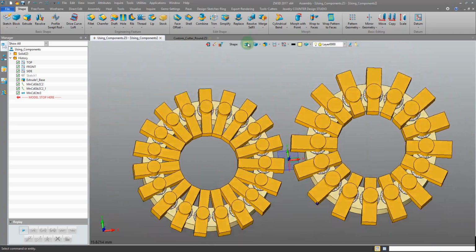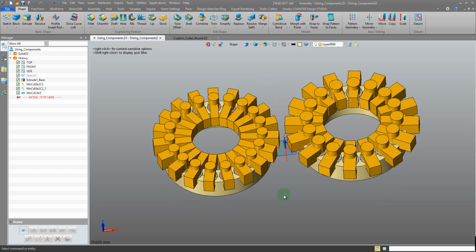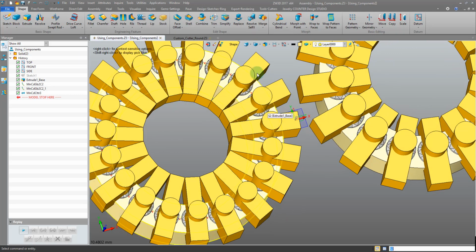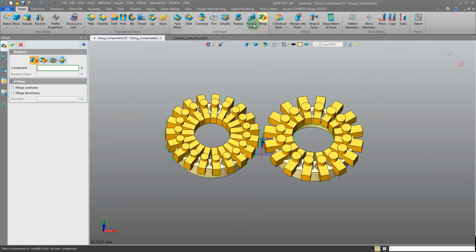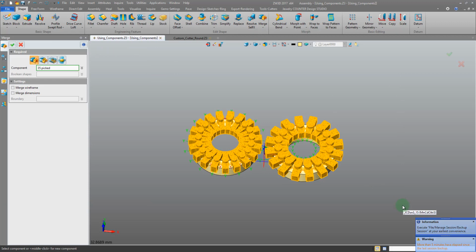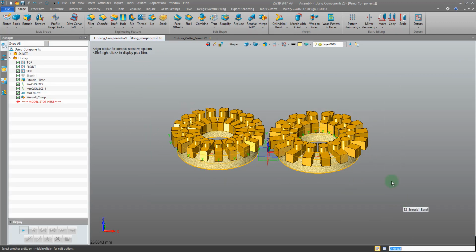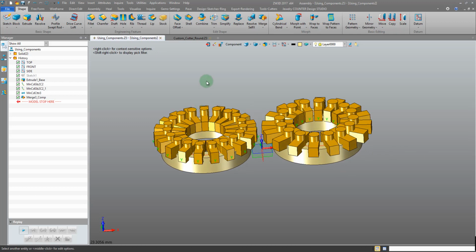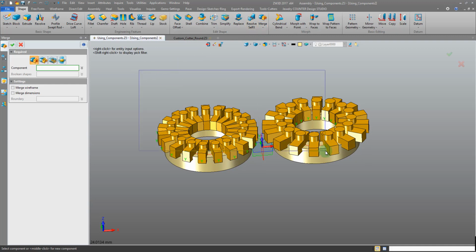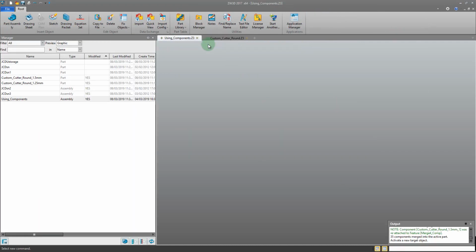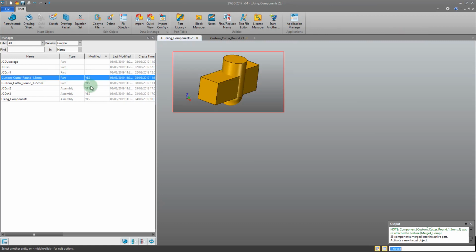This may work. The only step left to do is to remove these cutters from our shape to cut out that material. So that brings up an interesting point, and that is if we are to just merge our, let me just hide the gemstone layer so I can window pick all of these components. If we merge all of these components and try to window pick shapes, we're seeing that they're not picking, they are still components. And the reason for this is that these are a component inserted with a component. So we actually need to merge twice. Merge them twice, and now they're shapes. The reason for that is that they are components or parts inserted as a component into our cutter, inserted as a component into our main build. So we had to merge them twice.